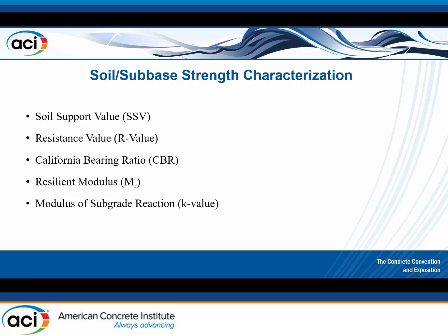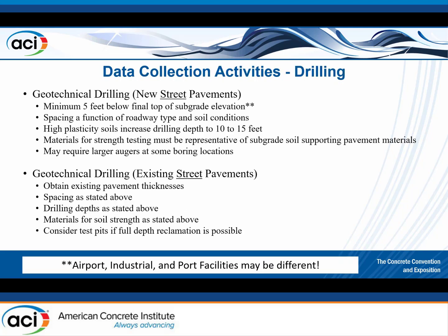But when we're characterizing the soil, we're basically trying to indicate how strong that soil is, right? A lot of times we just do the heel test, right? So we'll just kind of stick our foot down in there and press on it with our heel. And so do we indent it or do we not? You know, is it really strong or is it not? This is a way in which we can get some sort of an engineering value, or something that's correlated to an engineering value, to tell us how strong that pavement is. So we'll talk about those in just a minute.